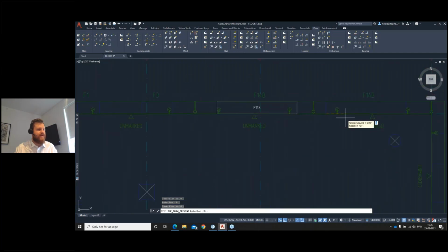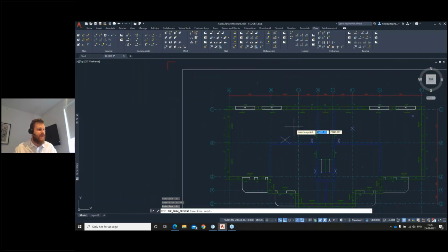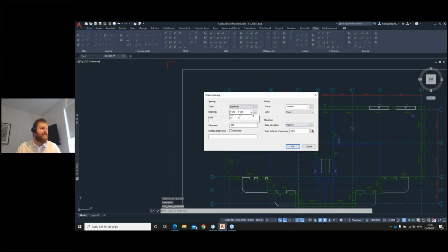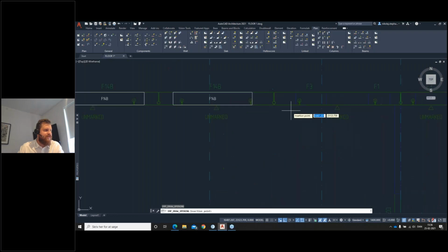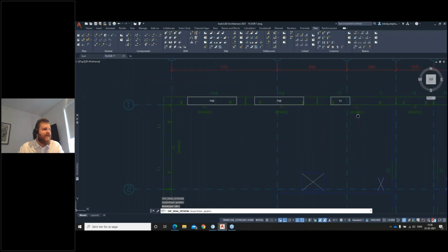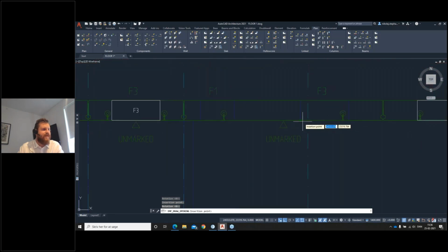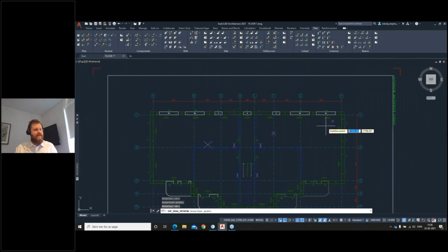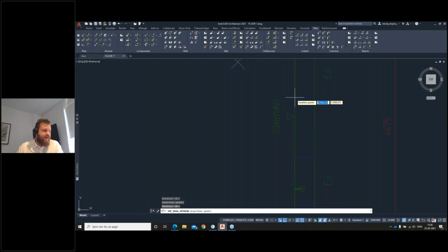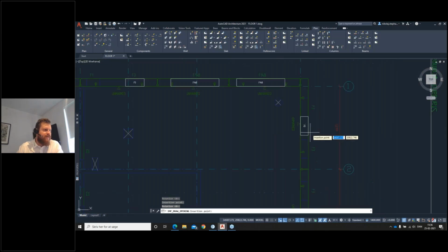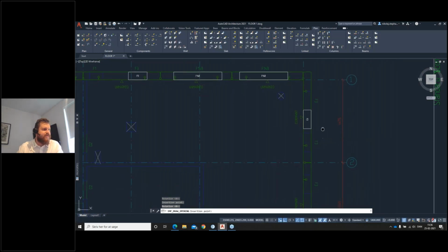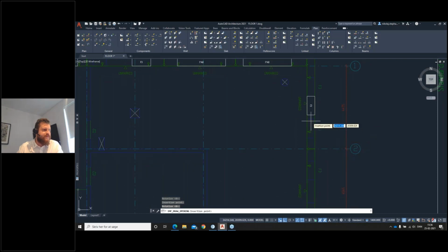So you can see now it makes them white. What does white mean? Well, it basically means that I'm inserting them into the model itself. And afterwards, I can attach them to the elements. And then if I move the elements, they will follow the elements. And you can see I'm zooming a little bit here, and that's just to help myself snapping a bit more precisely.